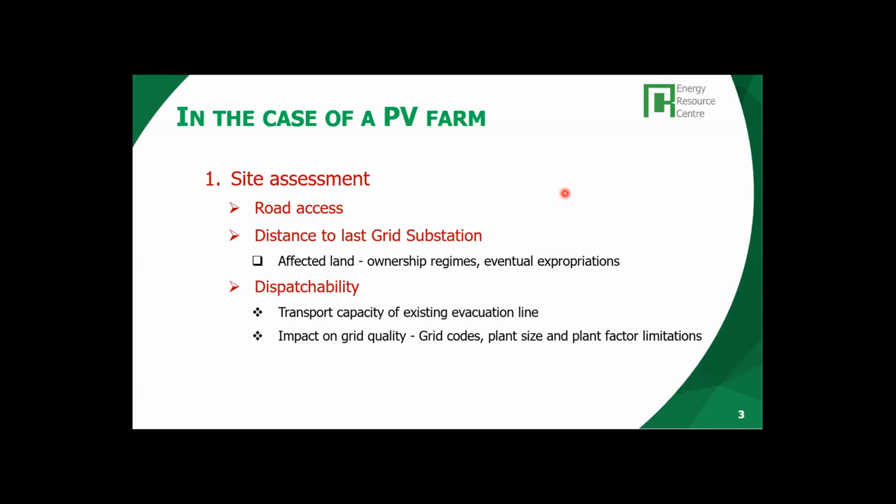Also, how is the grid, the transport and distribution grid, arriving to that particular site? What are the capacities of the grid around that area? What is the distance to the last existing substation at the moment?